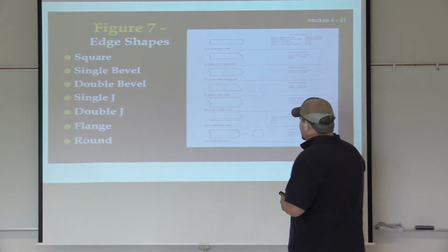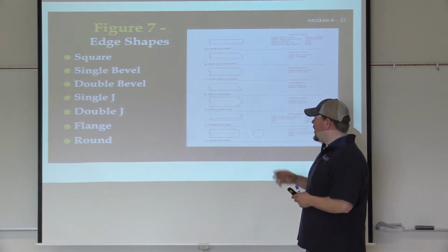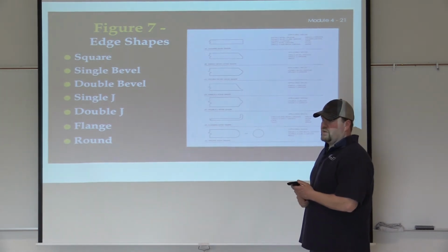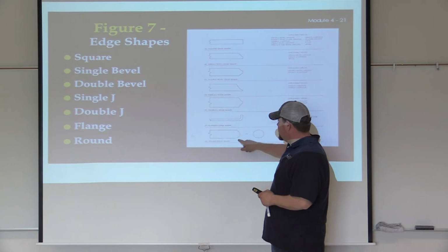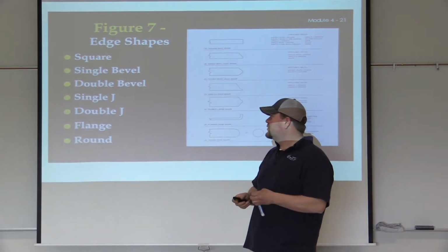Because at this point, it is technically a flare bevel or a round up next to a square. Instead of being a square butt joint, it's now a flare bevel, which basically means we have a problem getting in here. We have to watch our prep and everything else, okay?